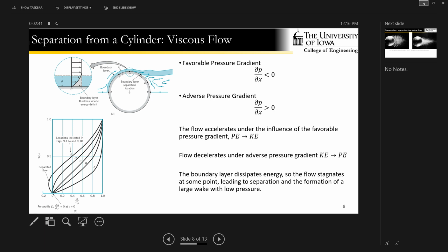However, the boundary layer is this sort of energy-robbing, heat-generating nuisance that turns some of the kinetic energy of the fluid into thermal energy that's not recoverable. So now if I'm a particle at point C, and I march along to point D, I would like to slow down and have the pressure increase, but some of the energy necessary to do that has been turned into heat.